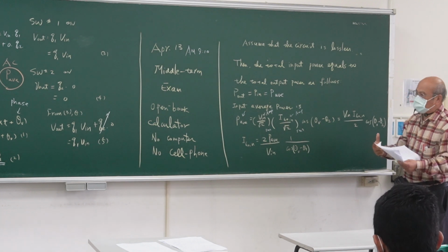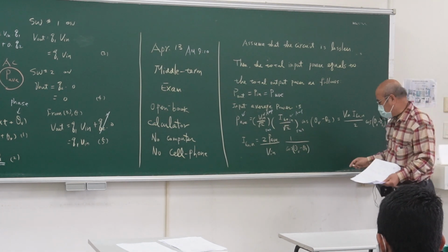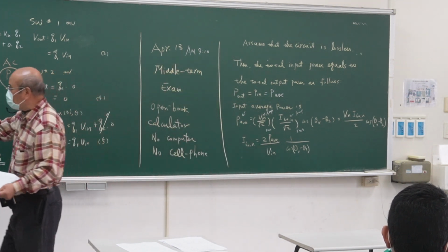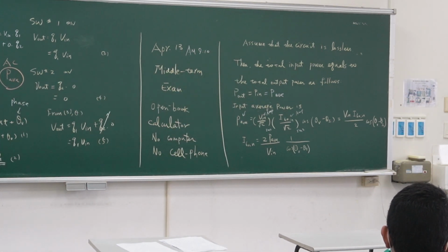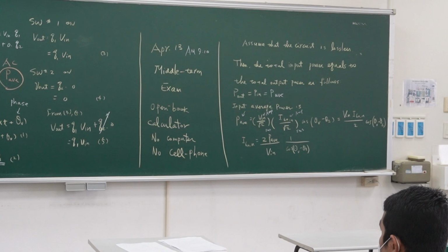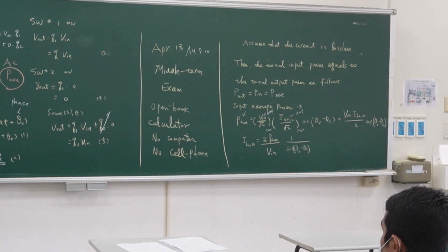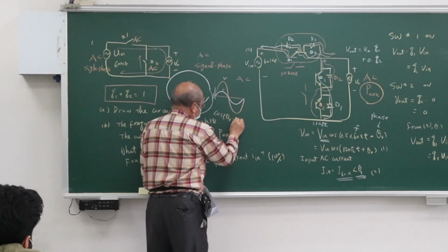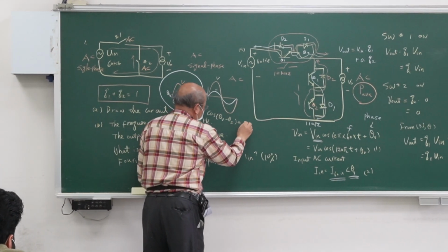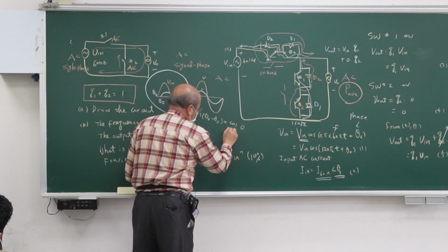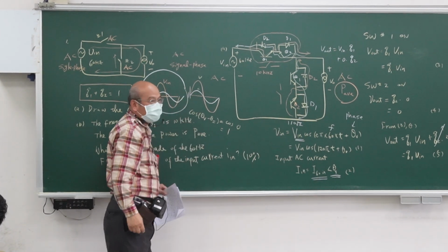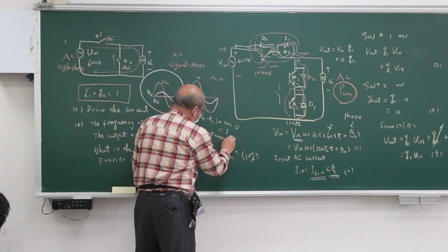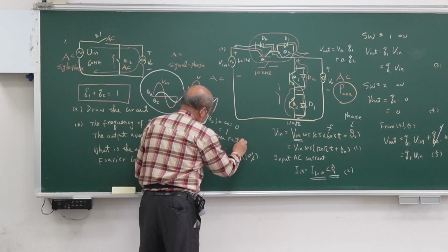So this is the circuit, and we can use the switch to do the phase shift. If we make the voltage and the current in phase, then cosine theta V minus theta I becomes cosine 0. Cosine 0 is 1, then we call this power factor correction.